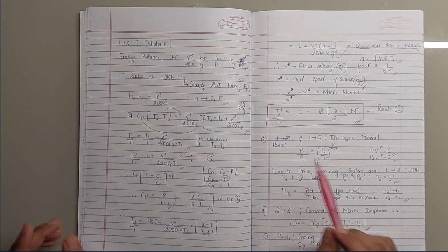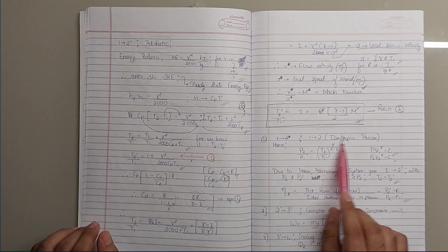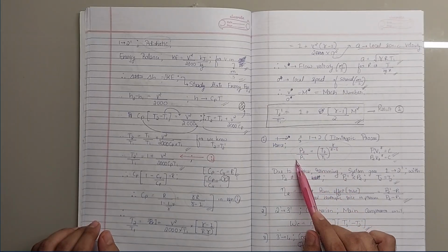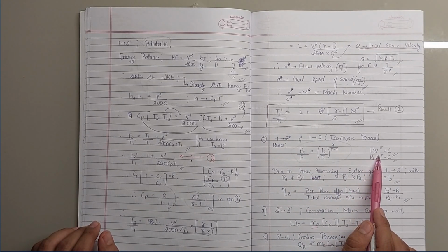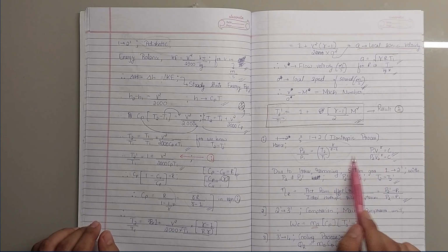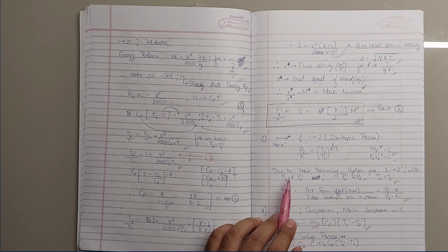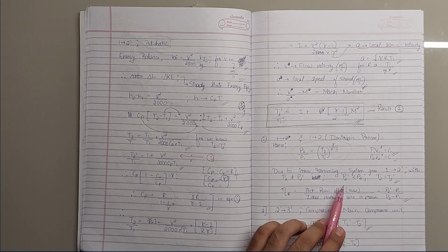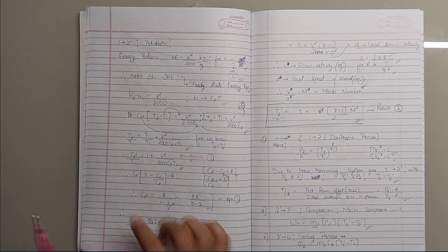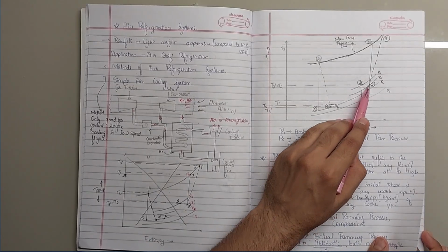Now we'll go into detail about each and every process. We'll go 1 to 2. 1 to 2 is an isentropic process wherein we can use the following equation. Isentropic process means PV raised to gamma equals a constant. We make V the subject, put it into this equation, and we get this identity. Due to the irreversibility in the system, as we discussed earlier, the system goes from 1 to 2 dash instead of 1 to 2 as we see here. It was supposed to go here, but due to irreversibilities it goes like this.